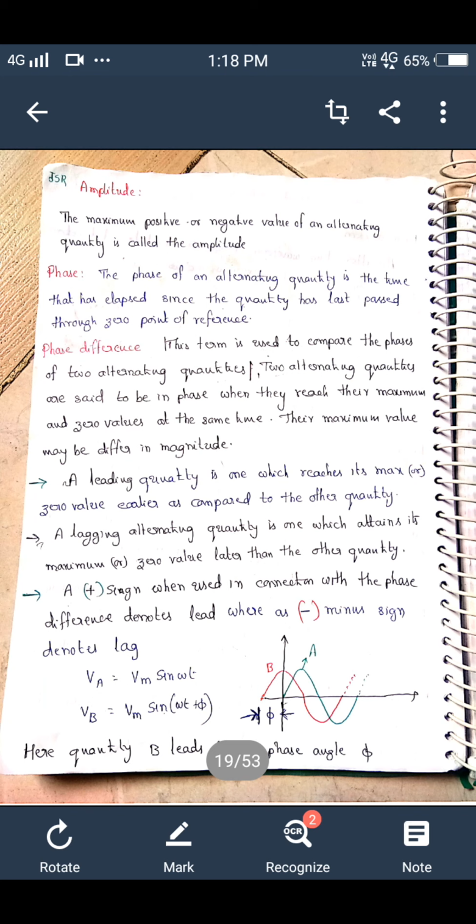The conductor has to rotate with a certain speed. Frequency is a speed-related term. Say the conductor is the rotating part and the magnetic field is stationary. If the conductor is under the north pole, the positive half cycle will be generated. When the same conductor is under the south pole, the negative half cycle will exist. So if the conductor completes one revolution, it gets one set of positive and negative cycle. Per second it has to complete 50 revolutions, then you get 50 Hz frequency.